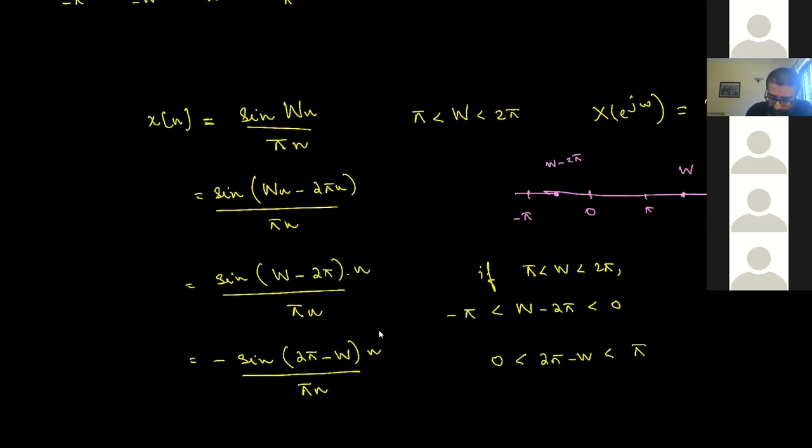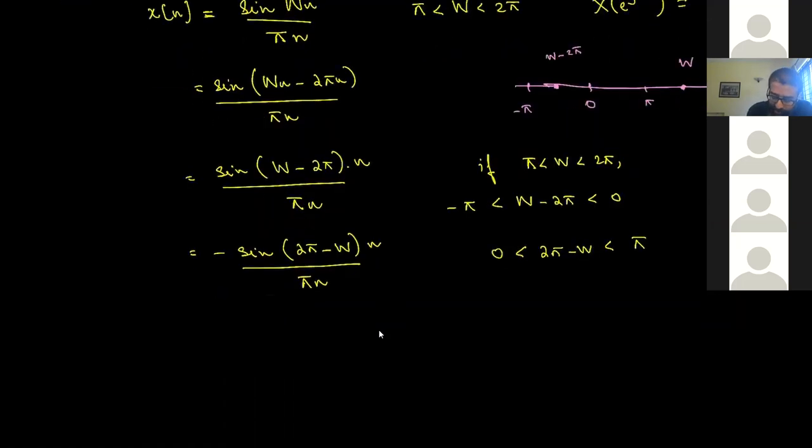Now you're looking at a sinc pulse whose frequency is between 0 and pi. So what will its Fourier transform look like? Now Seth, can you tell me what the Fourier transform is? The Fourier transform will reflect along the x-axis, so you'll get an inverted sinc function. Inverted rectangular. Oh, yes. Okay, and what will its cutoffs be?